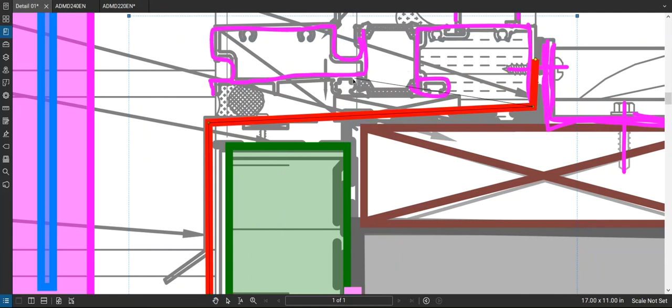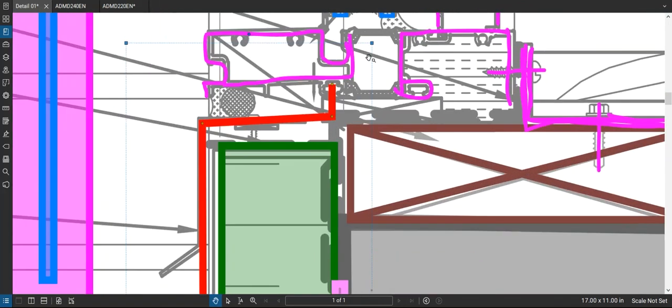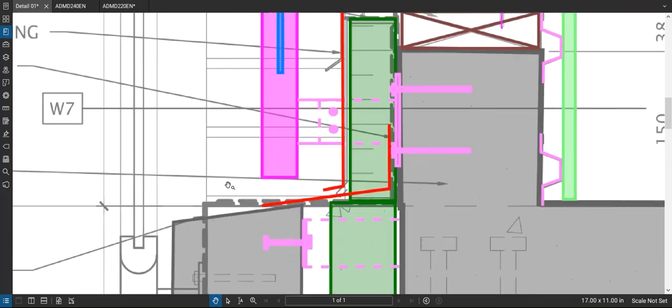But seeing that they have a weep there, I kind of suspect there's probably a place to tuck some flashing into, like so, with the intent of moisture not to get back into here, but again, maybe this extends all the way back right here. The flashing is going to have to work around that knife plate, but that's just life. Some stuff like that happens.